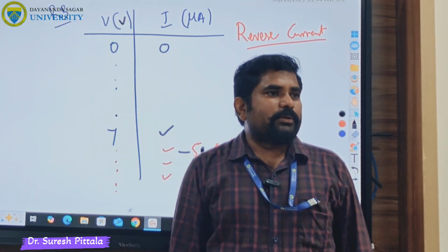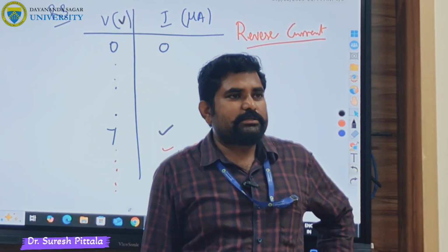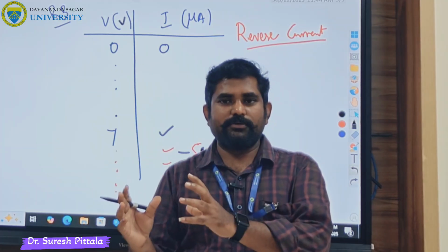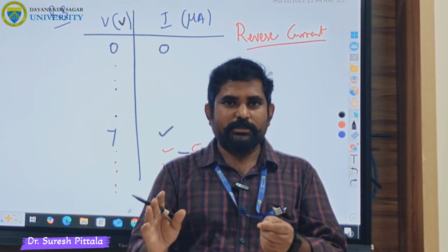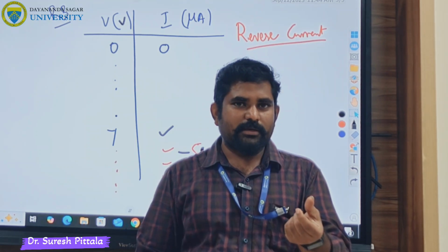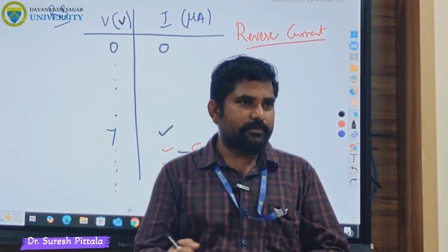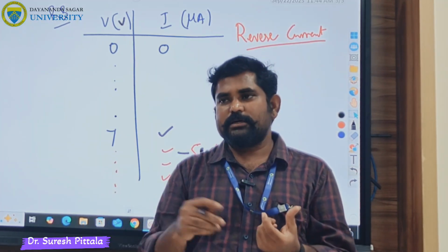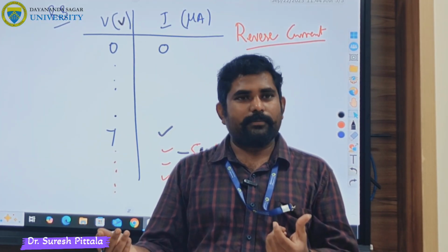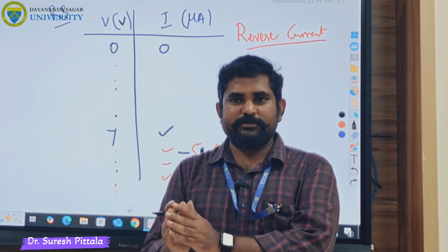Right? So in both cases, our experiment is done. What we are verifying in both cases is that we take a Zener diode and connect it in the forward bias first, a simple connection. Then you slowly increase the voltage. You need some kick to send the electron to the other side. Slowly increase the voltage and see how much current is flowing in the forward bias. Once the current reaches 20 milliampere, for the safe side, you stop the experiment.